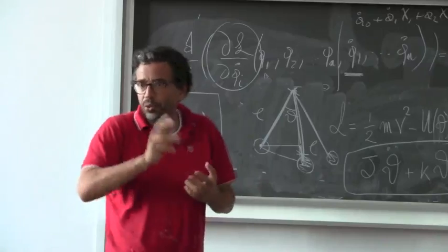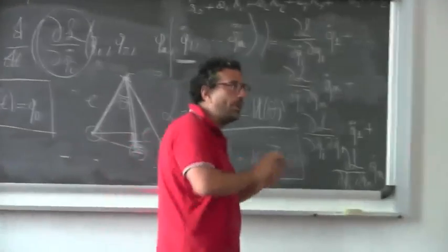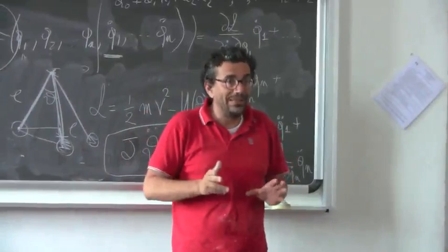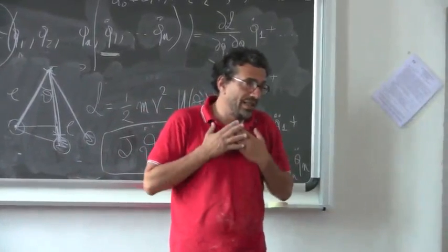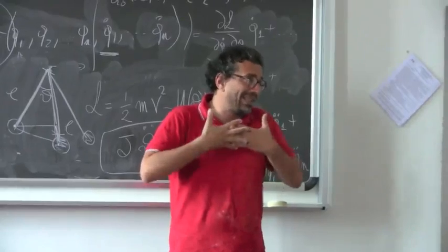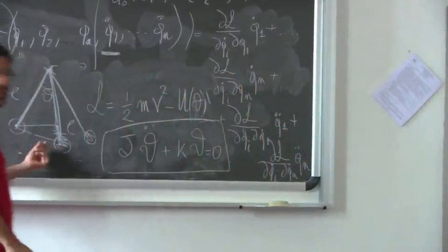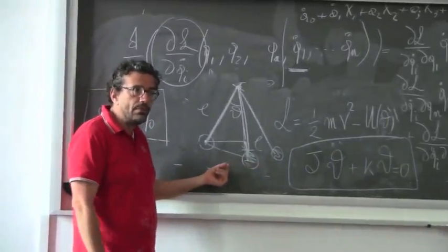I mean, you need to know which kind of external actions you apply to that bridge, and then you must calculate a priori that every externally applied action is not moving your system too far from the equilibrium condition.